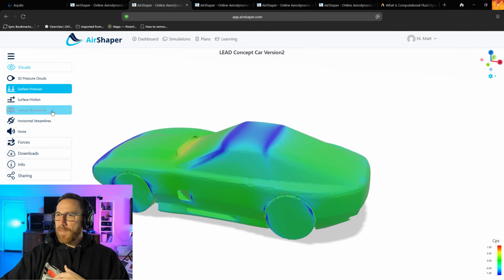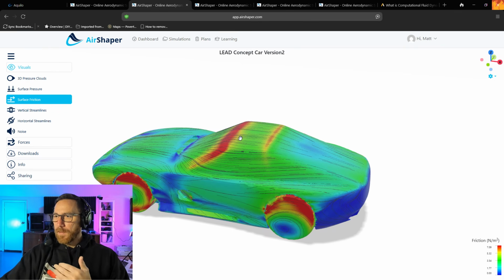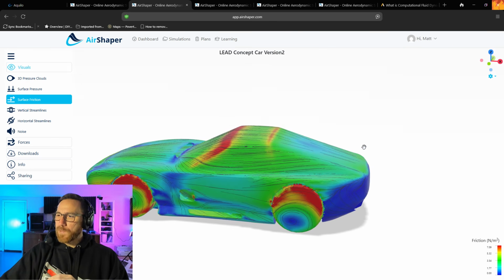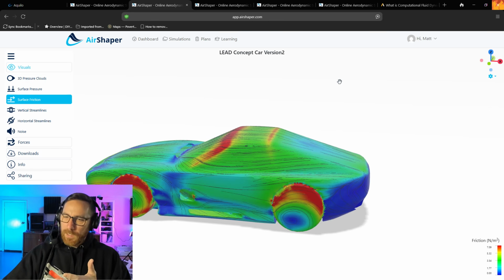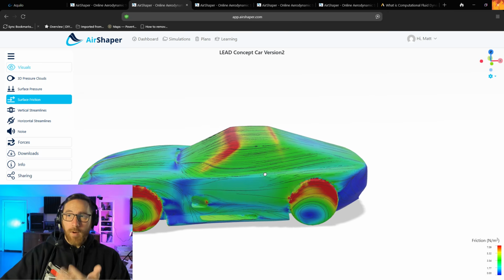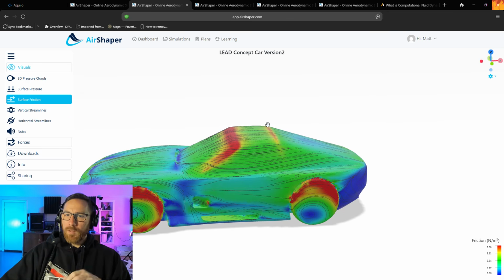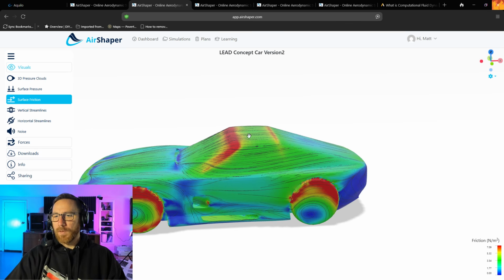But from the feedback on the results, having that sharp corner actually led to air separating away from the vehicle and coming back. So once there was a spoiler there and we're trying to manage the downforce, having that feedback was helpful. Again, the consultancy is based on credits. The low res solve is typically 1 credit. The medium, which is most of the ones that I did, were 10 credits, and an hour of consultancy is 10 credits as well. So just keep that in mind.